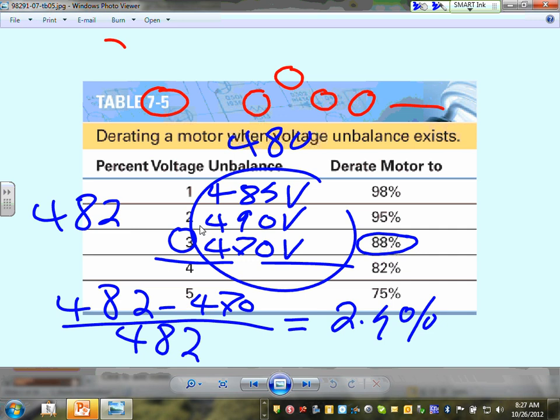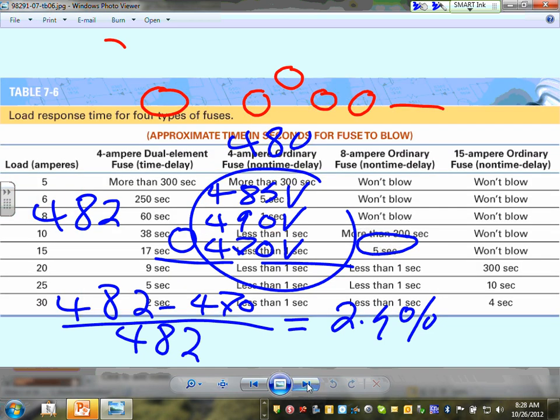Do you understand what an unbalance in the voltage is? You want your voltage to be balanced within 3%. So 2.5 is fine; within 3% balance is good. But an unbalanced system, voltage-wise, is bad news for you. How do you get an unbalanced system? If certain feeder phases are overloaded and the others underloaded. That's why balancing your phases on the three-phase load is essential. It's foolish to put a single-phase panel in a three-phase system, like we talked about before. So that's a couple of calculations.